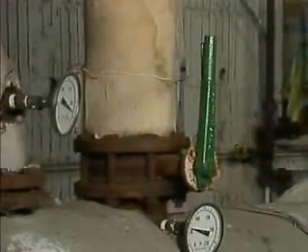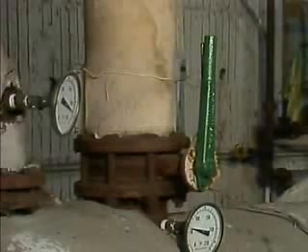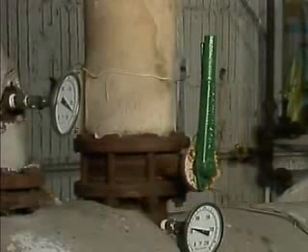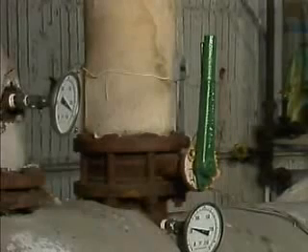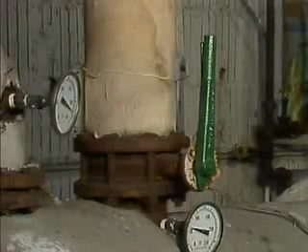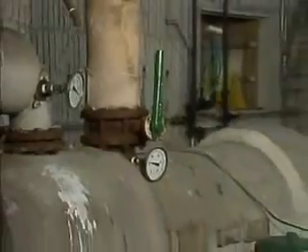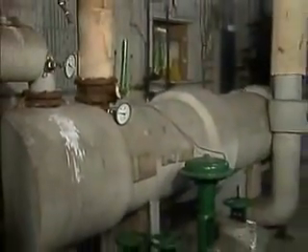This is a butterfly valve. Butterfly valves may be used for various purposes, but they're normally restricted to low-pressure, low-temperature systems, such as a low-pressure gas line or a cooling water system. They're particularly useful on large volume systems where space is limited.